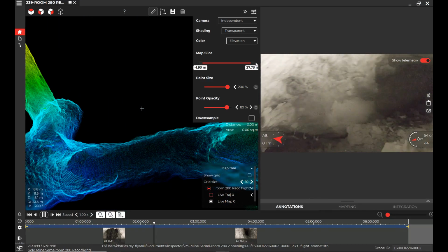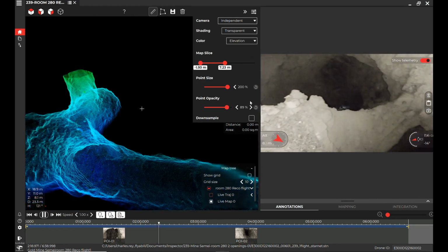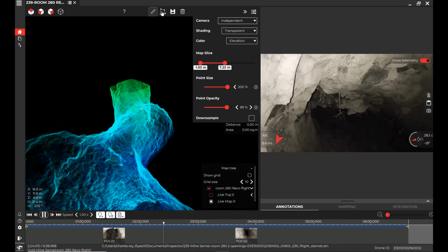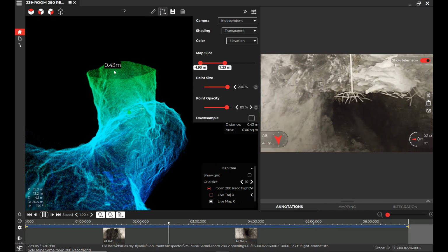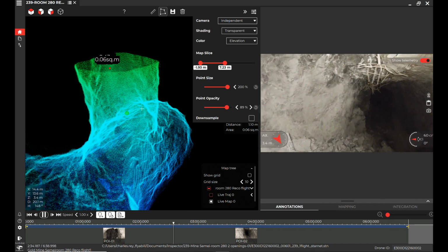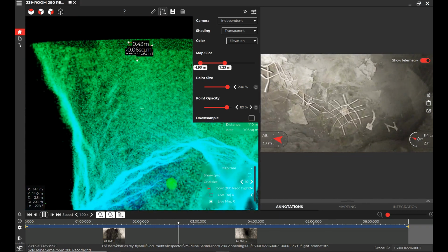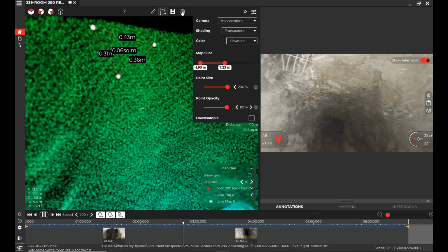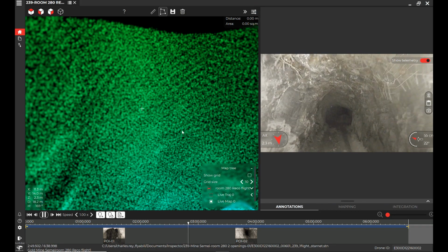The second tool, on the right of this one, is the measurement of a surface, of a polygon. So here I'm slicing the map so we can really see it directly in the blueprint, in the point cloud. I can select 3 points, and I can see the area in square meters. I can keep those measurements on the model by clicking on the small saving button on the right at the top of the screen, or I can remove them with the trash bin.